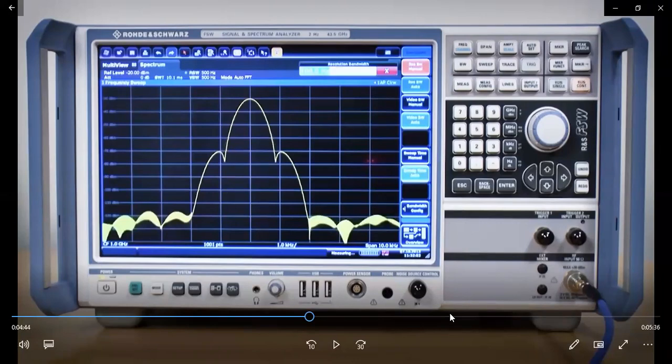That filter will be 3 kilohertz wide when you set RBW to 3 kilohertz. So for this small bandwidth, 3 kilohertz, you check how much power you have and then put a dot on the display. For the next 3 kilohertz, again, you determine how much the power level is. And accordingly, you set a dot or indication on the display. For every 3 kilohertz, you are performing the power level detection.